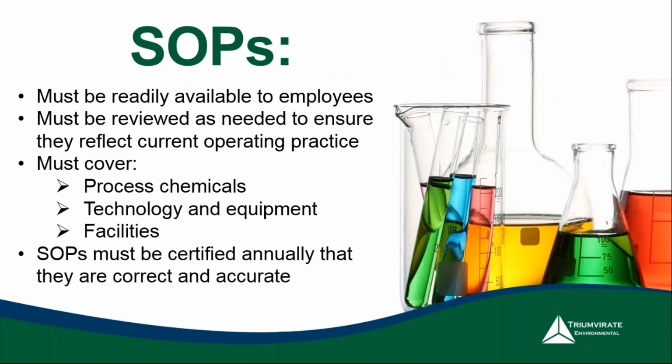All right, so then you got your standard operating procedures. Again, more of them, right? They're very similar to a safety data sheet, right? They got to be ready, available for your employees to see. They got to be reviewed to make sure they are current. So I typically like to say, hey, annual is great, but sometimes, depending, remember what it said earlier on the PHAs, it depends on the complexity. So at a minimum, you're going to do it annually, right?